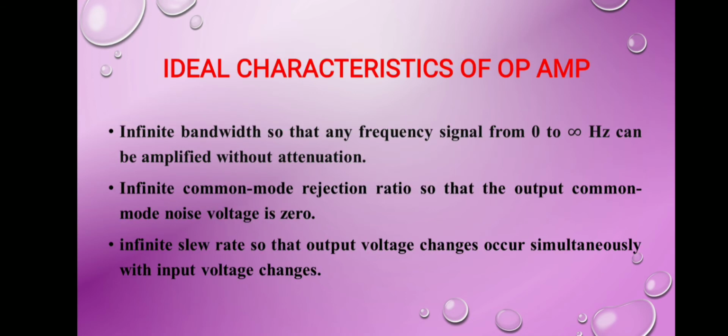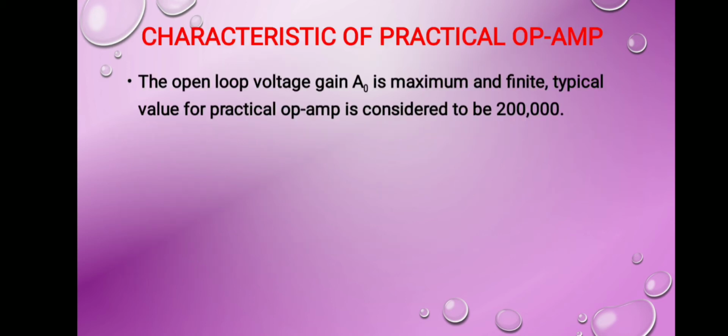Infinite bandwidth, so that any frequency signal from 0 to infinite Hz can be amplified without attenuation. Infinite common mode rejection ratio, so that output common mode noise voltage is 0. Infinite slew rate, so that output voltage changes occur simultaneously with input voltage change.